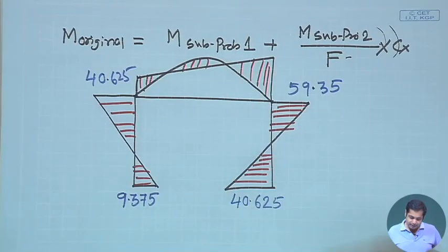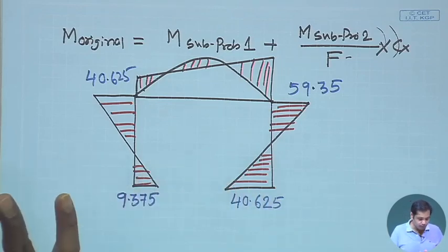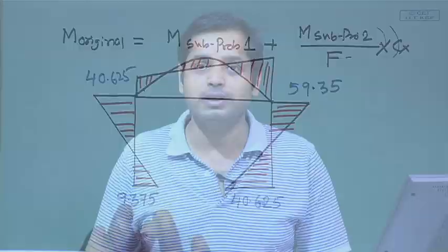Okay. So, essentially if you have a sway problem, then that needs to be divided into two parts. One is the structure without sway, and the structure where only sway takes place, and because of the sway, whatever moments you have need to be calculated, and then that moment needs to be normalized based on the reaction that you get in subproblem 1, and then finally you add the moments in subproblem 1 plus the normalized moments in subproblem 2 to get the moments in the original structure.